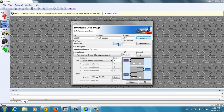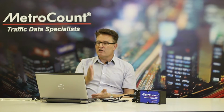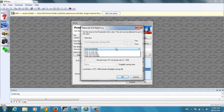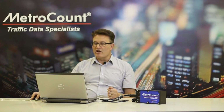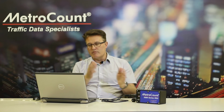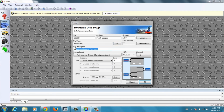Start time. The default is immediately, and really there's not a great deal of reason to vary that. If you're doing a number of surveys in a day, you might like a clean start to all your traffic surveys. So you could choose, for example, set to start on the next day, which would mean the loggers will all start at midnight tonight. But I'll just leave it as start immediately, and you have other options there as well. Most people would use start immediately. You can always adjust the start and end time in the software during data analysis, so it's not mandatory to have a clean start and finish time.